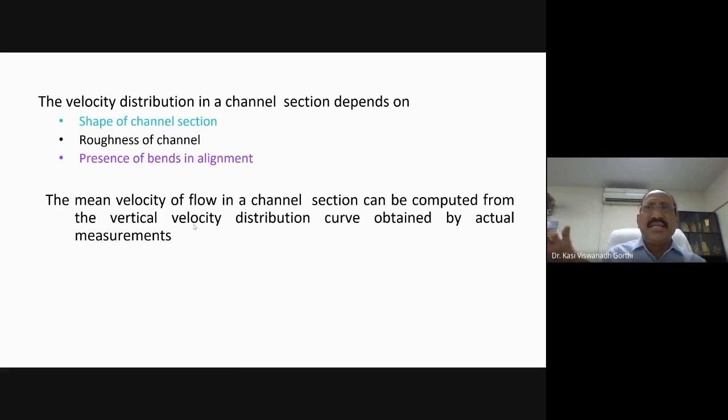If the flow is taking place in an open channel in one direction, facing that flow direction, you have to keep this tube. Corresponding to the velocity here, there will be an increase in the water level in the Pitot tube, and you will be able to get the measurement h. So root 2 gh, of course multiplied with a certain coefficient, will give you the velocity v.